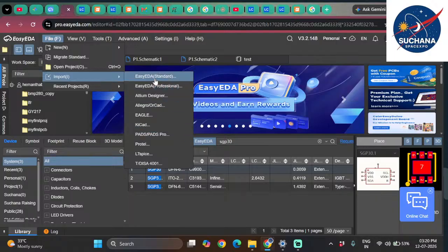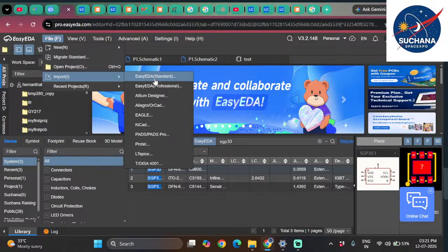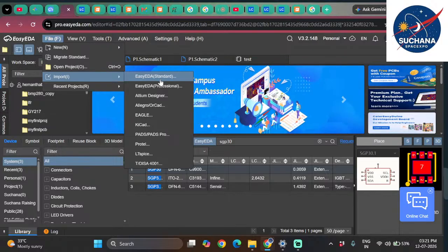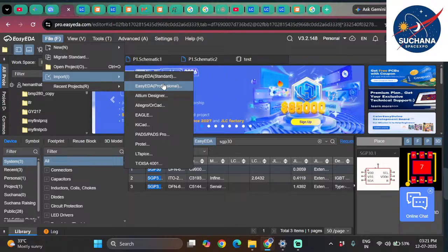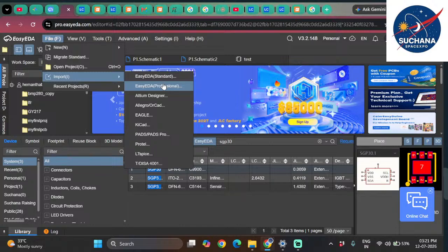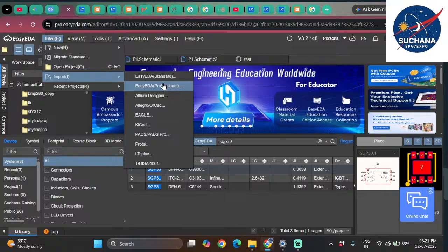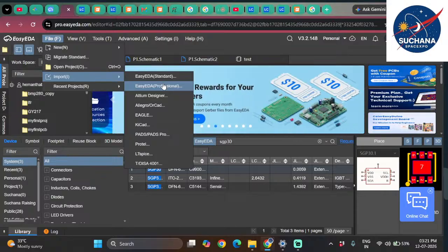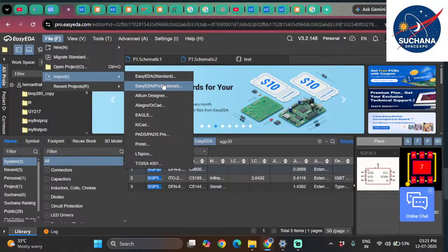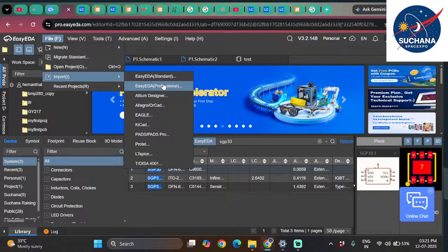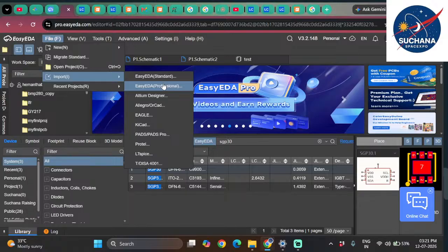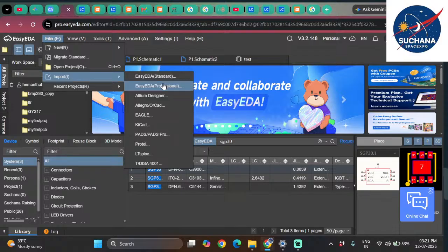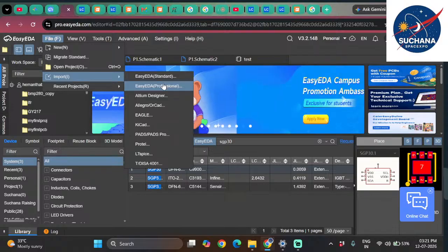What we are discussing right now in the beginner session, what we discussed in the last 30 days about EasyEDA, is just to introduce you to how PCB designing works, what the workflow is, and what the different steps involved in making a PCB are. We gave you a lot of theoretical knowledge, starting from the manufacturing process inside a factory, the chemistry behind the etching process, copper traces, how to determine the width of the copper traces, silk screen layer, gold fingers, and along with these we discussed a few DRCs, design rule checks. What DRCs we should follow if we are using a gold finger.